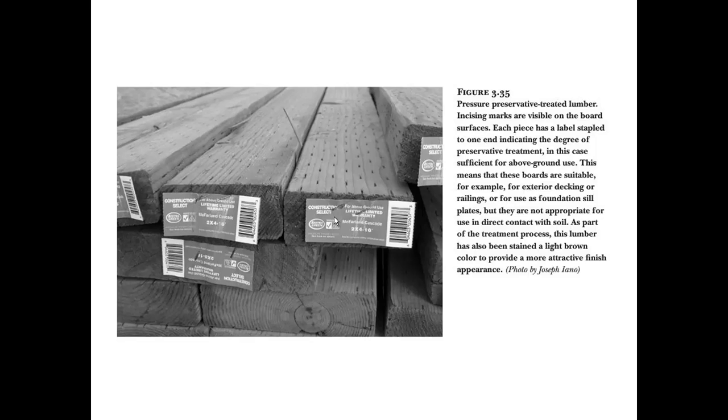We use a lot of pressure treated lumber for decks and sills and whatnot. This is just an illustration here of what are called incising marks, which are used to pressure impregnate the wood preservative into the wood. Most of your better pressure treated woods, when you look at the tops and bottoms, you'll see these little teeth marks on them, and what they're doing is actually digging into the wood with these teeth and injecting the preservative deep down into the grains rather than just painting it on the outside. So when you see those, it isn't a defect in the wood, it's actually how they put the pressurized preservative into the wood material.